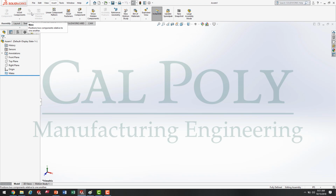Then it's got linear motions in the X, Y, and Z axes. So 6 degrees of freedom, 3 linear and 3 rotational. So we have to constrain a part's degrees of freedom with respect to other features on other parts in order to assemble an assembly in the assembly environment. Might have sounded confusing right there, and it is until we actually do it. So let's try this out.